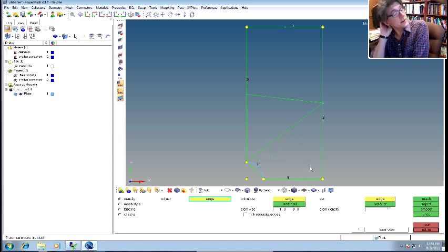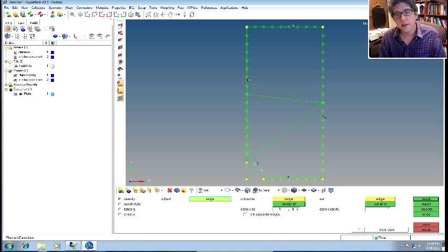This is something that you want to really get to learn how to do in HyperMesh, because the quality of your mesh is really important. There's a couple of things that you can do. One is element density, and then there's element size. You can set globally the size of an element. So let's set it at like 1. Then if I do recalculate all, you can see it starts to give me a hint of the element distribution. So I can do a reject, throw out that old mesh, and do a mesh.